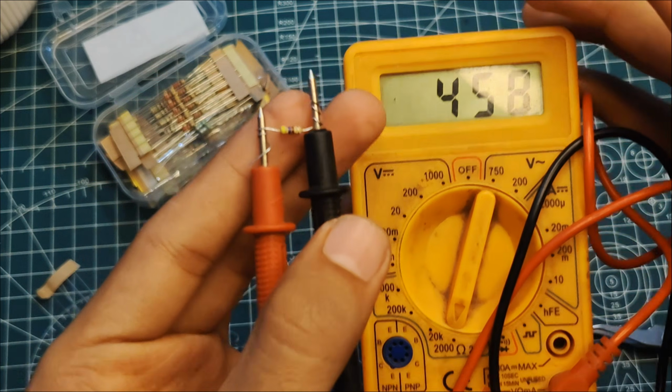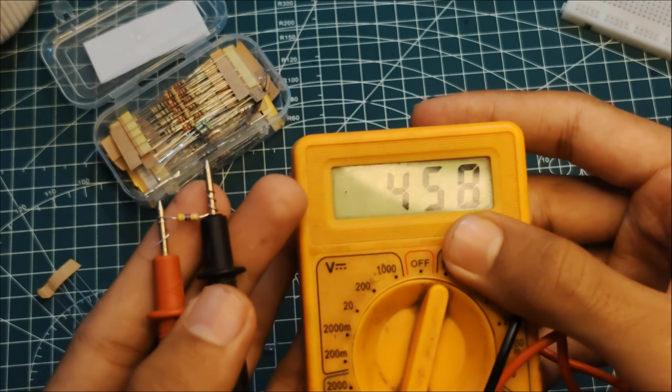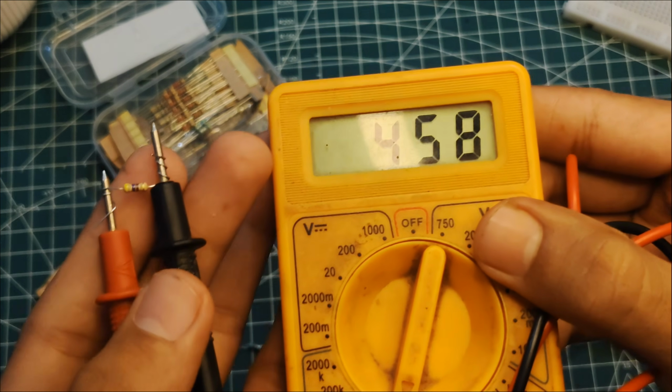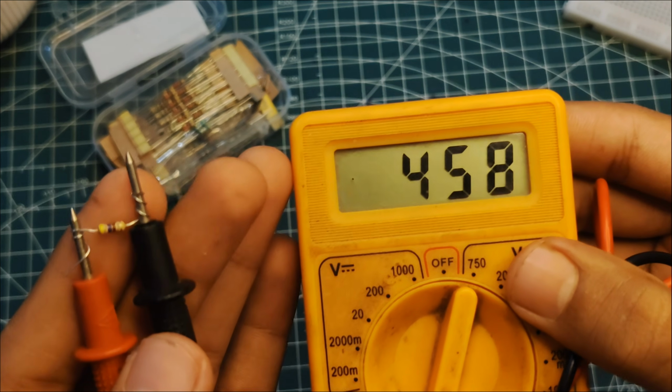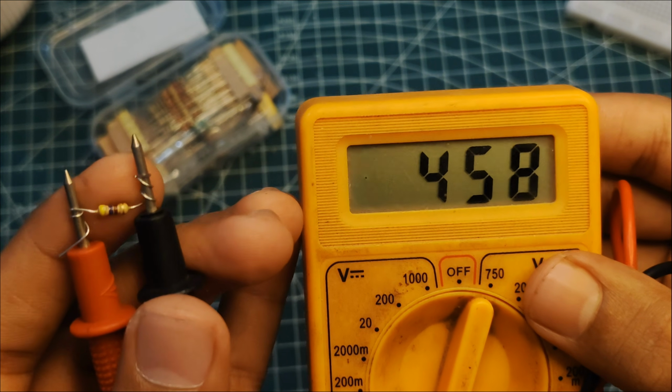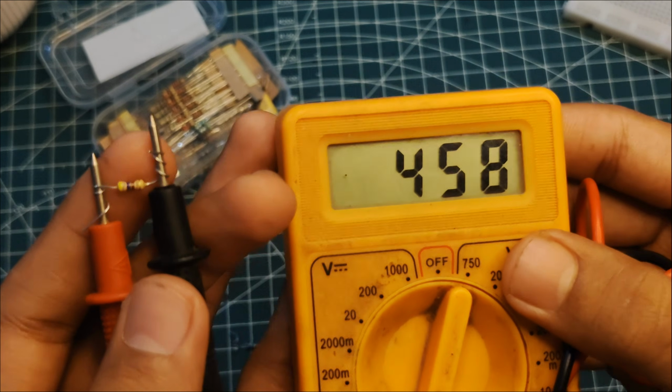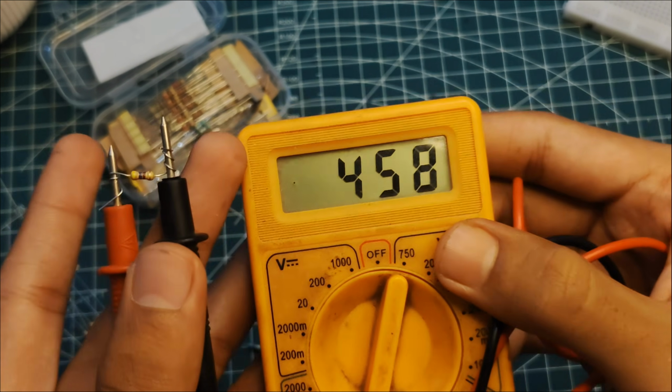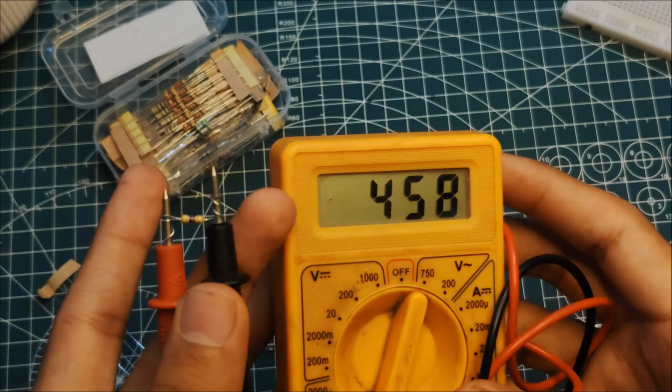So you can see here it has a 5% plus-minus tolerance. Here we got 458, which is almost close to 470, as I have a 470 ohm resistor. So this is how we can take the main reading using our multimeter instead of just going